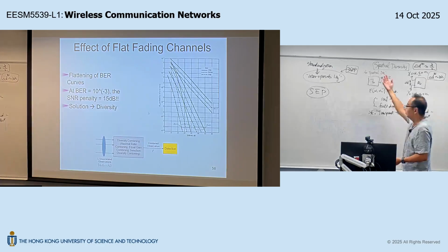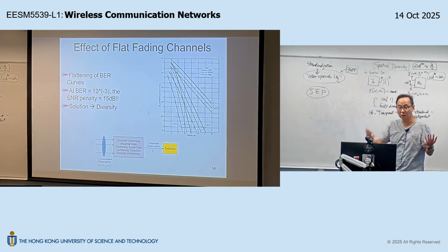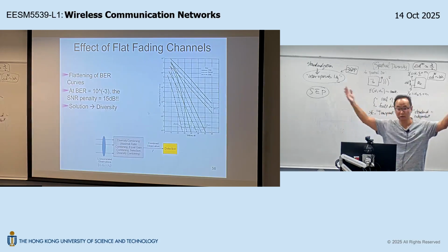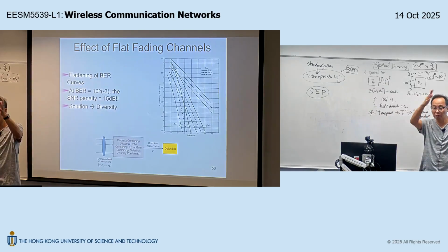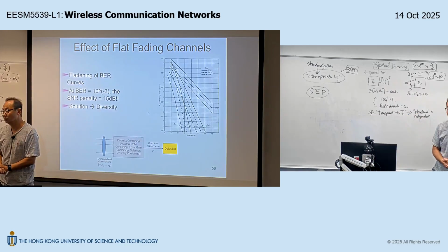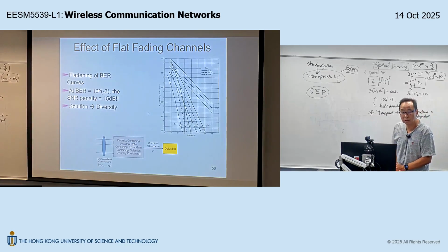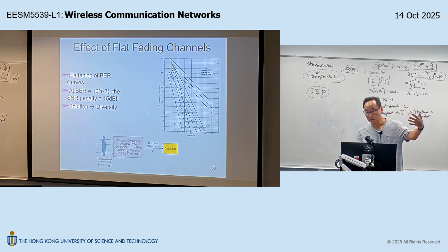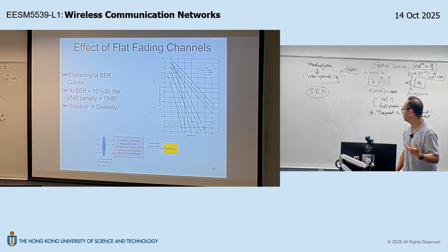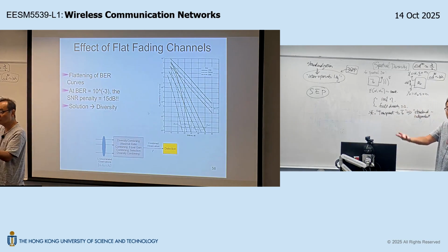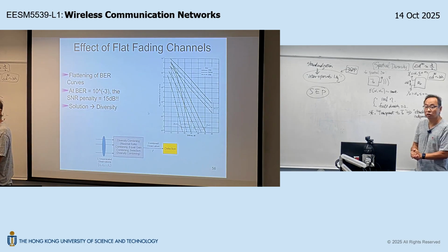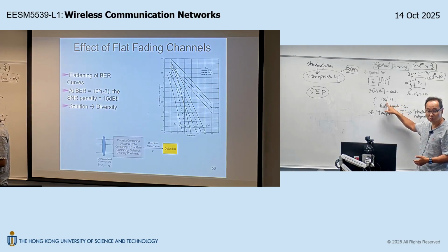You may think, how about I put multiple antennas on the transmitter side? The base station side usually has more space, right? Because it is mounted on the rooftop, you can have more space to install more antennas. So that was the motivation for considering multiple antennas on the transmitter side. And what they hope to achieve is called transmit spatial diversity. When you have transmit spatial diversity, what they hope for is that you can still achieve 100% spectral efficiency and full